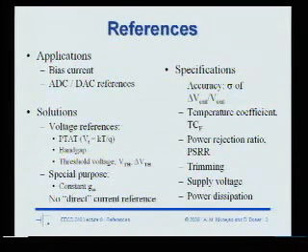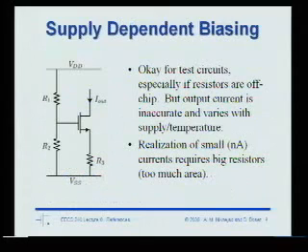So when you manufacture something, there's some trimming cycle where you measure an on-chip resistor and you have a fuse, or you have some switches, or maybe even a physical laser that comes in and changes the width of that resistor. These are trimming techniques to get precision resistors. Okay. And then other concerns are like, how much supply voltage do you need? How much power does it dissipate?